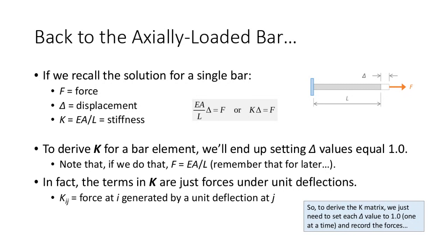But what I want to find is a stiffness matrix for this bar element. So for this problem, we're going to sequentially set each of these degrees of freedom equal to 1, then look at what the bar looks like, and ask, what forces would cause that displacement to happen? I'll walk you through what that means in a bit, but there are really 2 things I want you to make sure you have burned into the back of your head.